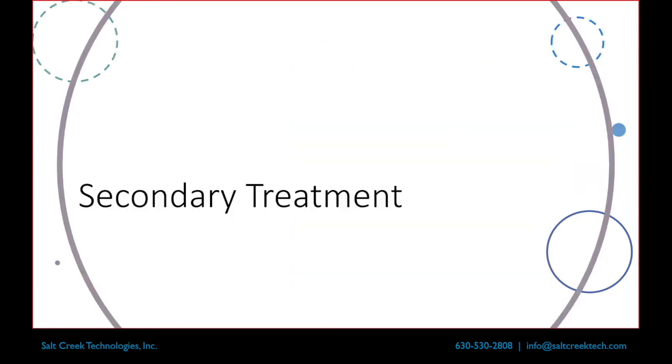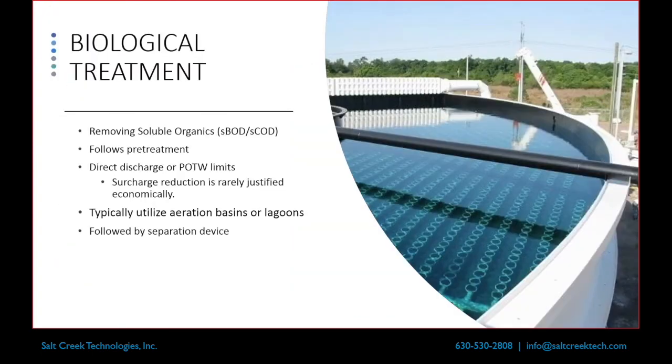Let's see, yeah, that's it. So secondary treatment, I think John did already a pretty good job of going through everything here. Just to repeat, it's removing soluble organics. So you're going to remove soluble COD, soluble BOD. It's going to come after some form of pre-treatment, unless you're making just a fluid product, like a beverage facility or something like that, where you don't have a lot of solids and it is all soluble BOD, COD that you're trying to remove.